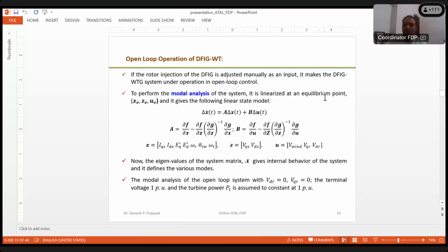Then if we talk about the mathematical analysis, every time we design some control, we need to take care of the stability of that. In my case, I am taking all the equations associated with the gear train, turbine, and generator. I have linearized them and made system matrices which reflect the characteristics of the wind power generation system. Accordingly, we come out with matrices A and B through linearization, which can be found by solving them mathematically.